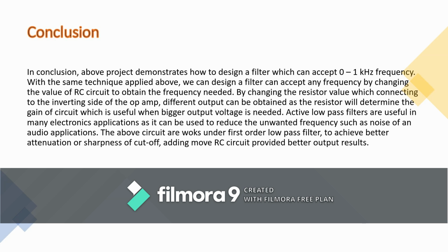Active low-pass filters are useful in many electronic applications, as they can be used to reduce unwanted frequencies such as noise in an audio application. The above circuits work as a first-order low-pass filter. So in order to achieve better attenuation and sharpness of the cut-off frequency, we can add more RC circuits to provide a better output result.